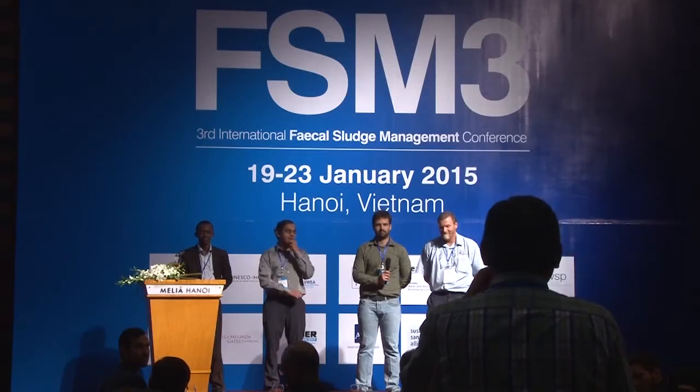Okay. So I guess the comment there is there's a lot of theory in other fields, including traditional environmental engineering, that we can apply. So we don't have to reinvent everything. And for Dave, what about pour flush toilets? When you open them up after they're dry, they're really like soil, and they've decreased in volume. But obviously there's a lot of water involved. And in an urban situation where we have pit toilets left and right and very high concentrations, you can imagine the water fields are very close together and maybe very saturated. What's your take on that in terms of transport of nutrients and pathogens?